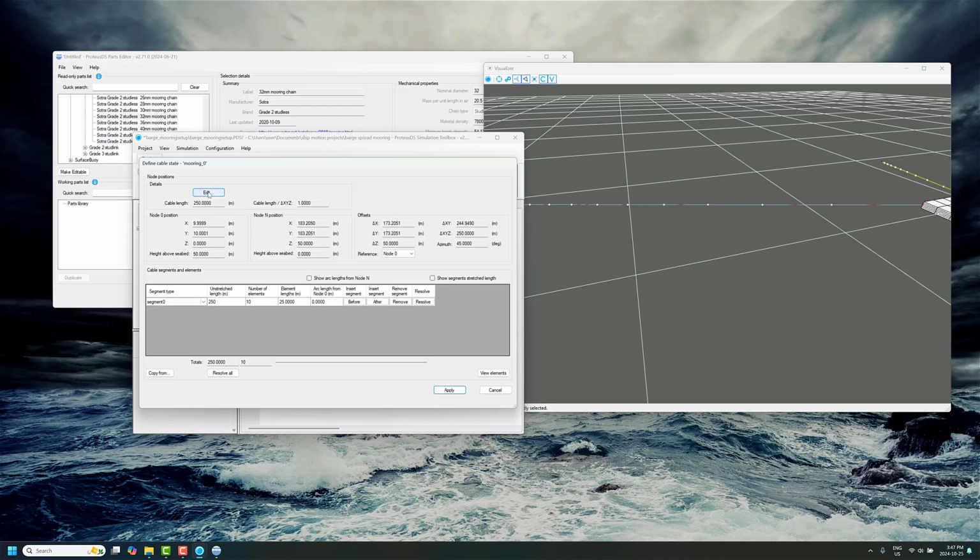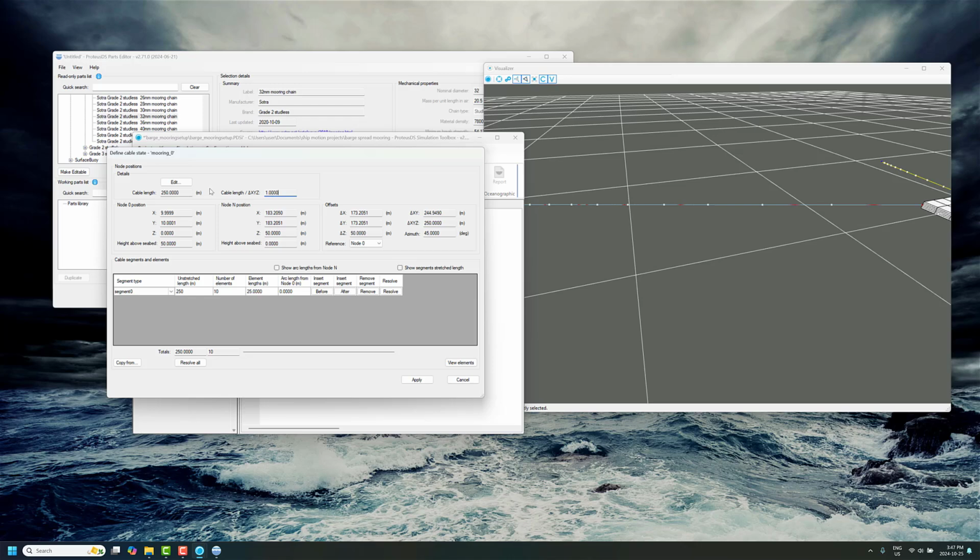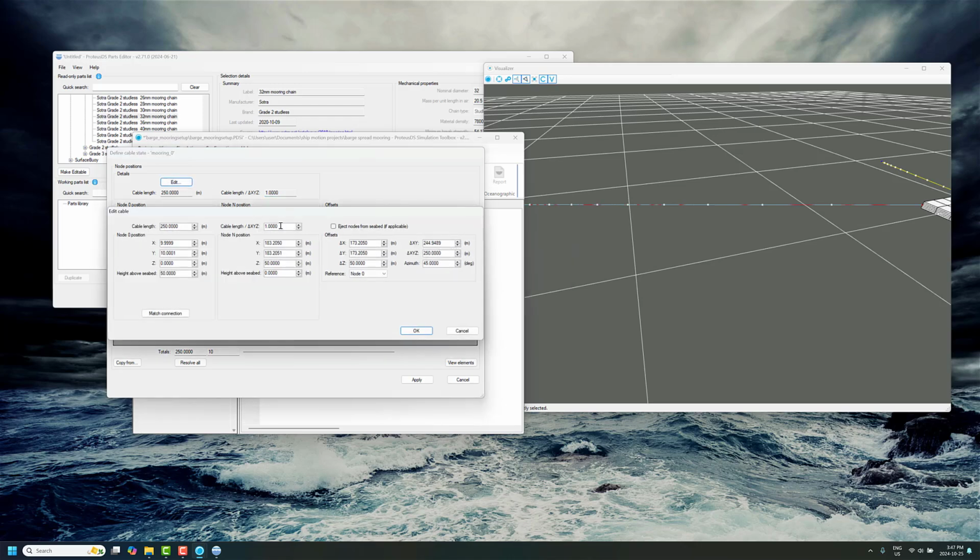What we want to do here, here's where we establish the geometry, which is going to show up as a blue line. We're just going to give the geometry a tiny, tiny amount of extra length in here, and it's pretty shallow, so it's not going to make very much of a catenary belly, even with just this little bit of extra. This is 1.0025. There's a little bit of a bow there, but with lifting up that chain, it's going to make some pretension in the mooring, and you'll get a feel for what value works for what kinds of projects you're working on.